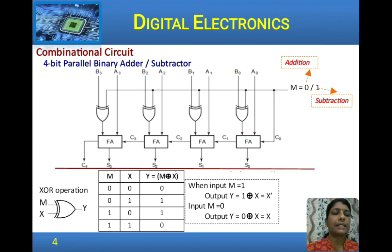Now to design a single circuit which will function both as an adder and subtractor, we have a 4-bit binary adder subtractor. Here we give an additional line M equal to 0 or 1. If the addition operation is to be performed, M is given the value 0. If subtraction is to be performed, it is given the value 1. We will see how a parallel adder circuit can be used for both addition and subtraction.